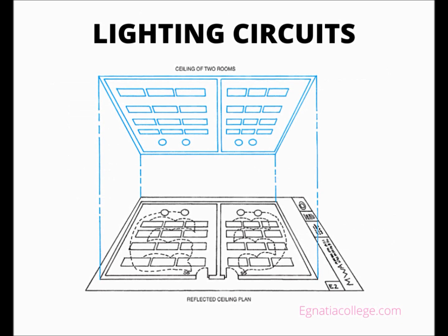This floor plan shows light fixtures, emergency lighting, security lighting, and special lighting control: photocell, motion detector, etc. Typically included is a reflected ceiling plan. That is, it is a plan view but shows what is on the ceiling as though it were reflected onto the floor plan. The reflected ceiling plan shows each light fixture with a circle, square, or rectangle that approximates the shape of the fixture.